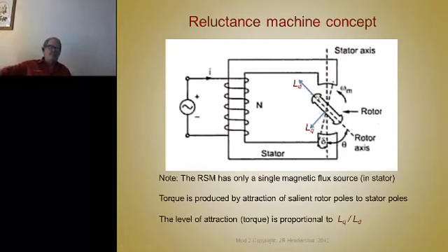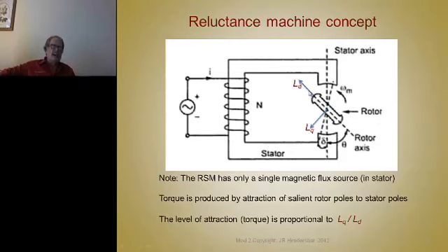And so if we position this rotor part on the shaft vertical like that, so that this is sitting in there and this is sitting in there, we have a minimum air gap in the circuit. We only have a tiny little air gap there and a tiny little air gap there. So if we measure the inductance of this inductor, it's going to be quite high, because there's very little air in the circuit. All the flux is carried by this permeable core, very high permeability as opposed to air. So there's going to be a lot of resistance to the current buildup in this. The L over R is going to be a big number. We call that inductance the D-axis inductance.